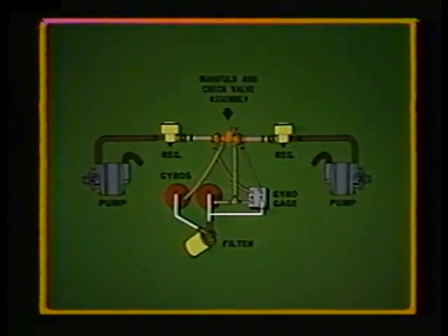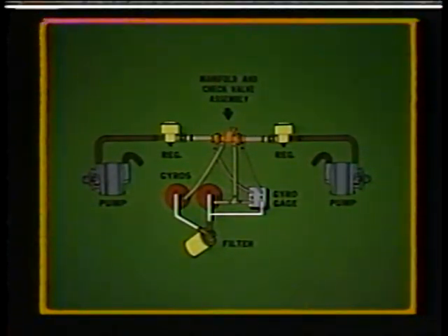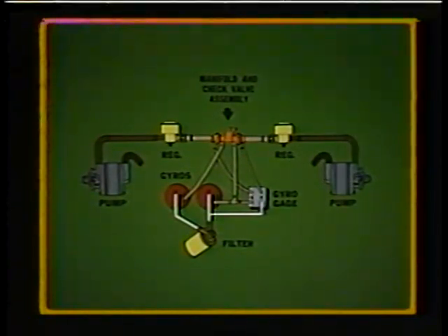In multi-engine installations, both vacuum pumps feed into a common manifold. This manifold has two check valves connected by lines to the source indicators on the differential pressure gauge. Both pumps supply the system. However, in the event one air source fails, it will be shown by the source indicator.